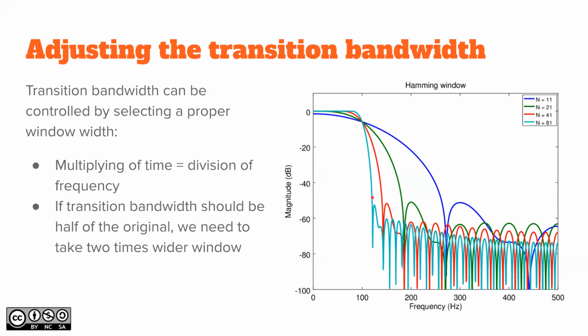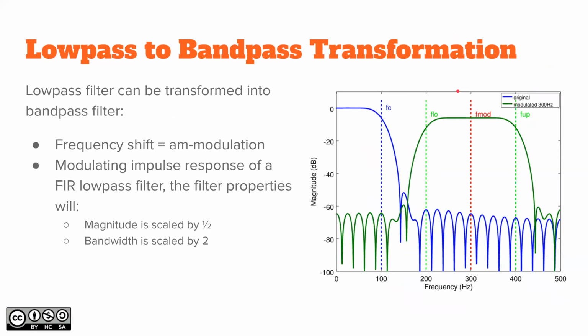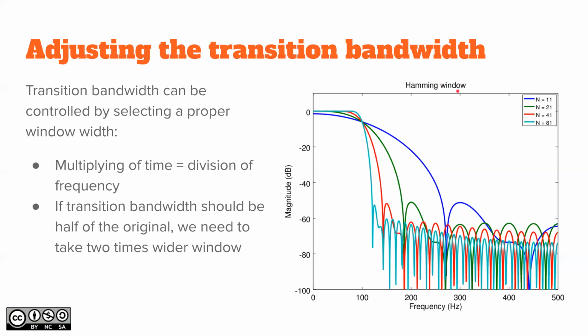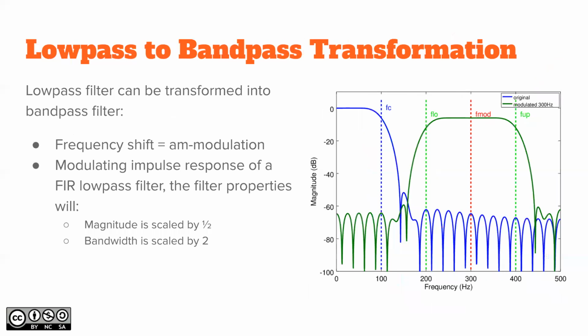There. If you need to have exactly something, then you design a filter with the correct sinc to get the cutoff frequency and the correct window shape to get the attenuation, and then you fix the window width by checking how much you need to go either down or up on the transition bandwidth. Okay. All right, so that was the low pass filter using the windowing method.